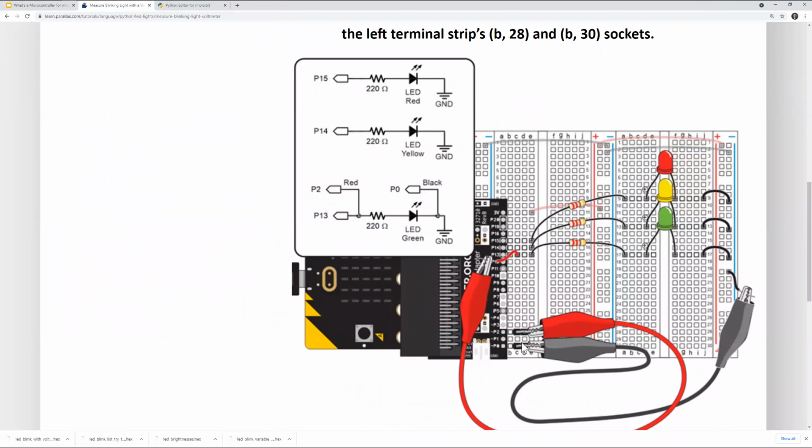So it's the alligator clips, the red alligator clip goes on the pins for P2. Black alligator clip goes on the pins that are by P0. And let's see, it is working, showing oscillated voltages of 0 and 2.74 volts. That is absolutely within the expected range of voltages. It would be nice if it gave us a nice clean 3.3 volts, but that's not in the cards for this microcontroller.